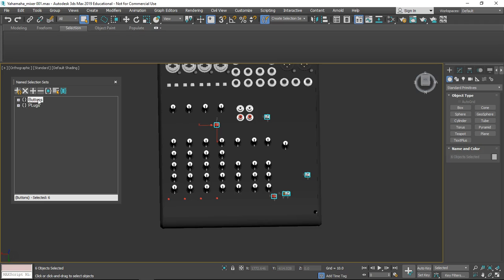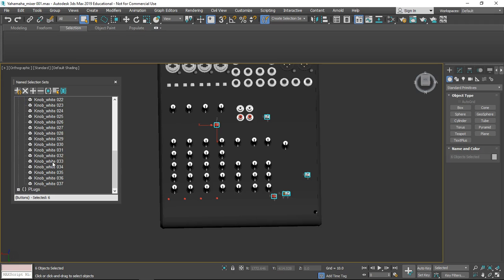So I have to come over here and I have to click buttons. I have to click the plus symbol, and you can see here's all the knobs, buttons, and there is the plus sign to add selected objects to this group. So we click add, and then you'll notice here we have our other push buttons. Push button 11, 10, 9, 8, and orange and regular. So now we've added that to our group.